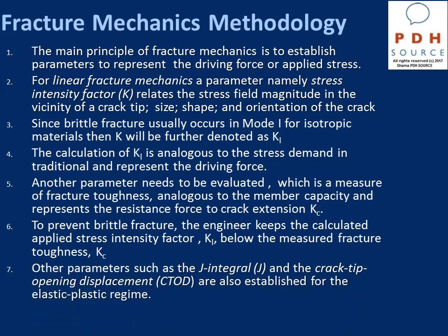There are other parameters such as the J integral and the crack tip opening displacement, or CTOD, that are also established for the elastic plastic regime. But we are going to focus mainly in this course on K sub 1, since we are dealing with linear fracture mechanics.